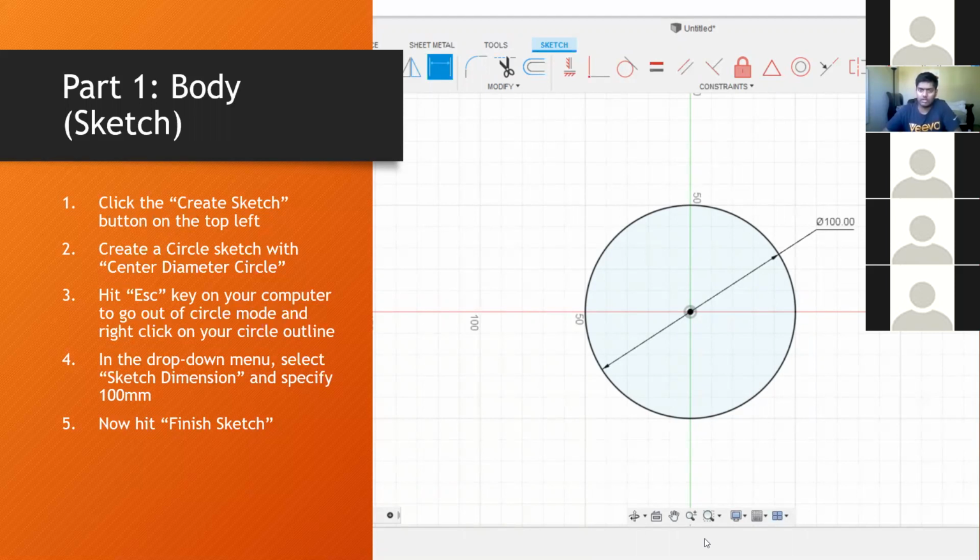All right. And now we're going to create the bottle itself. So we've created the cylinder, now we're going to hollow it out. And the way we're going to hollow it out is using the shell function. Now what the shell function does is it removes material from a part. So we're going to use the shell function and we're going to specify a face here.